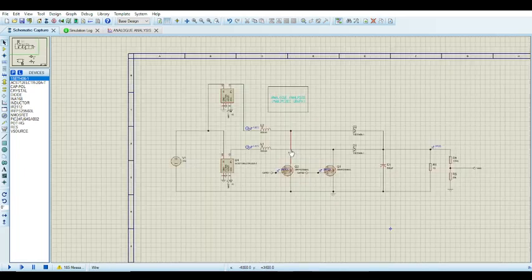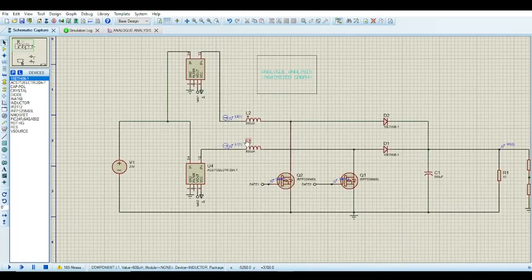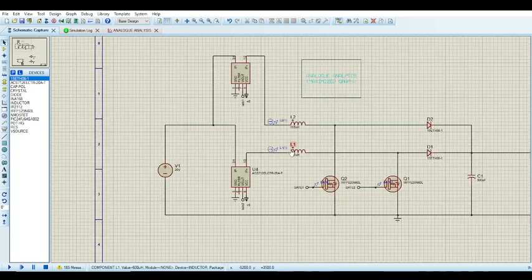But the most important thing is that your sensors are placed properly so that you can get readings into the microcontroller, because the code literally means nothing if the hardware is not giving it proper readings. So sensor placement is really important. And in the microcontroller, if your ADC is not working, there's no need to go ahead, because you will get absolutely nothing. Obviously, the ADC is very important in the functioning of control. And that's about it with average current mode control.